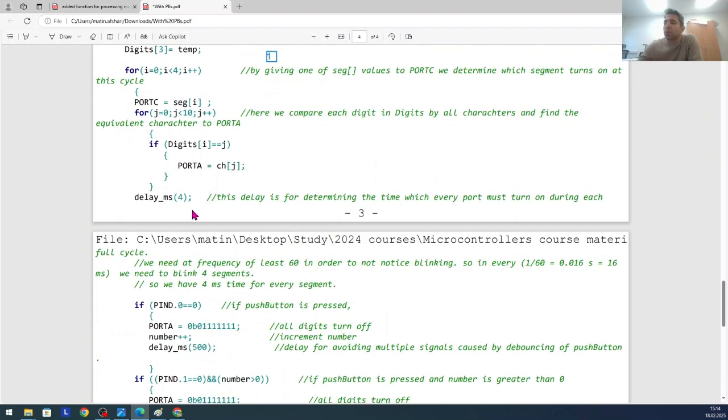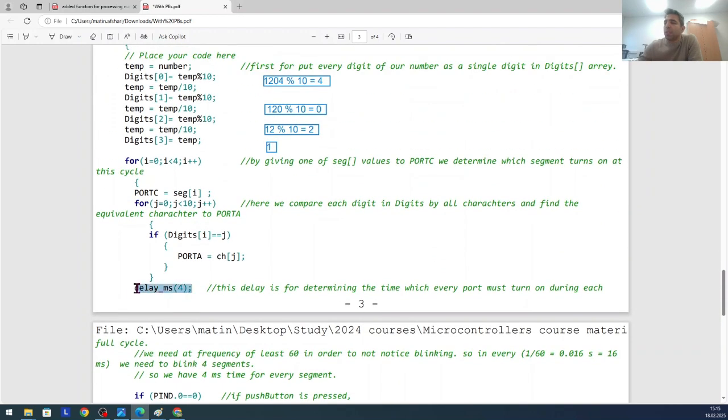We don't have much control. We put a delay of a millisecond here, for example, but it's not exact. But if we use a timer, we are sure that the timer does the interrupts after nearly every 4 millisecond. It would be much better to update, and we will get exactly 60 hertz there. Right now we don't know, because this is 4 millisecond, 4 millisecond.